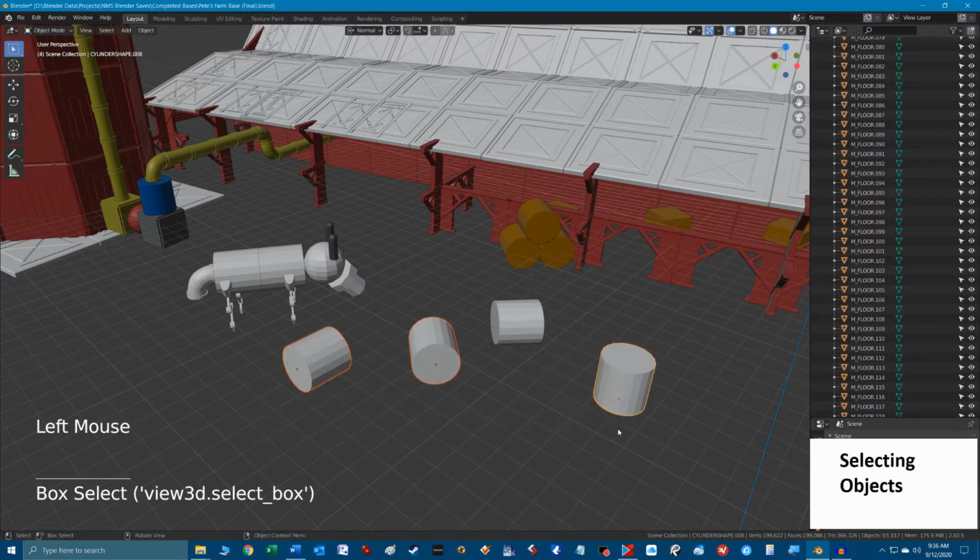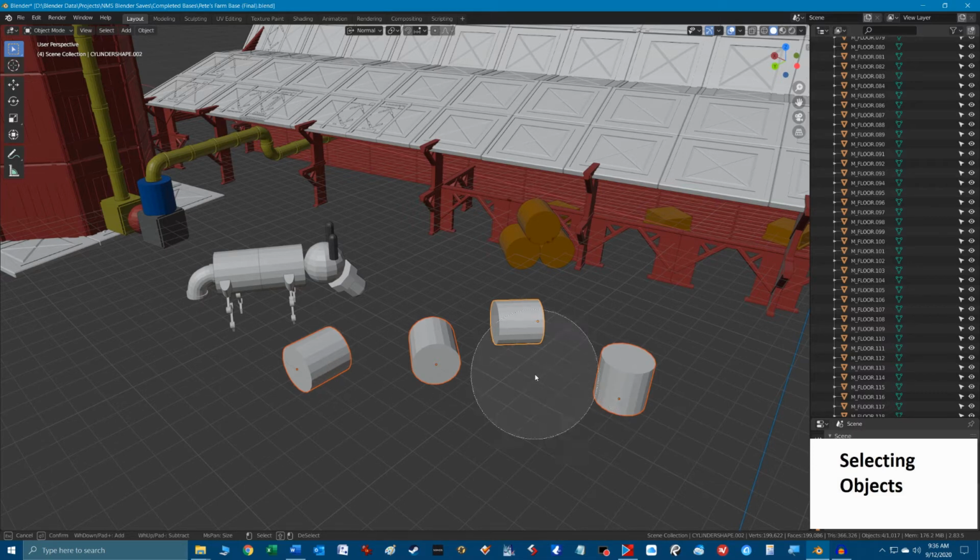I do want to mention one selection tool that isn't shown on this list but is available when you are in any of the select tool modes. This tool is activated by pressing the C key. It looks like a circle select tool and it works somewhat similar, except it's resizable, using the mouse wheel to increase or decrease selection area. And the selections are automatically cumulative. To unselect objects without impacting the rest of the selection, hold the Alt plus left mouse click. To deactivate this tool, click on the right mouse button to cancel.